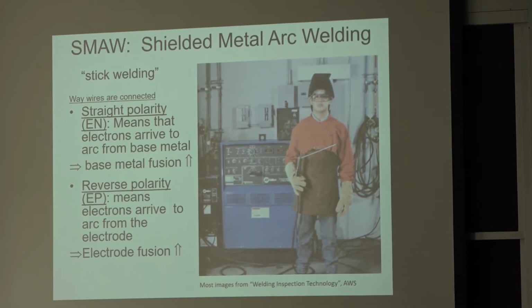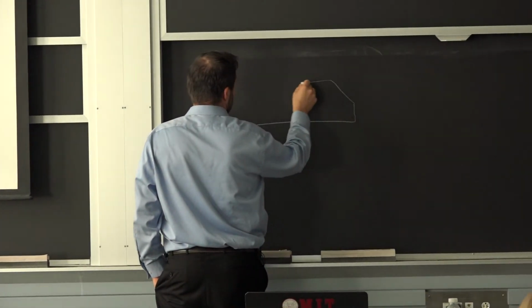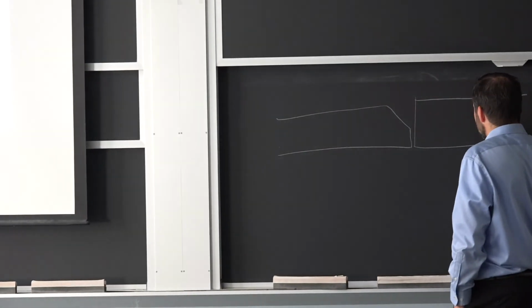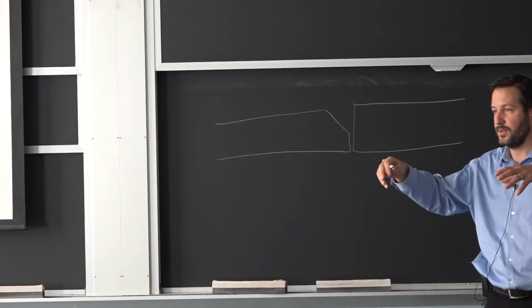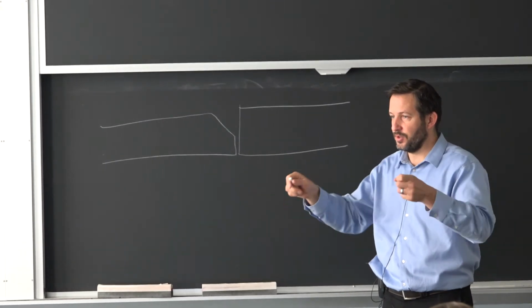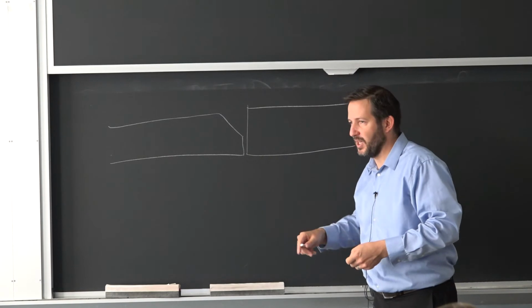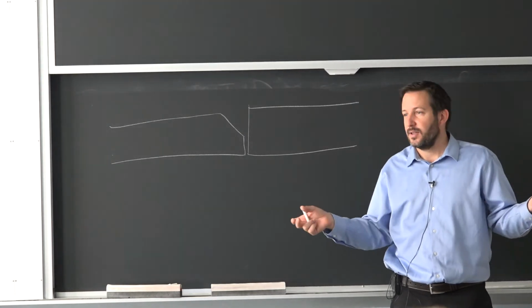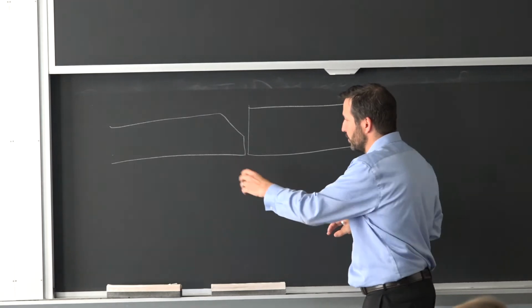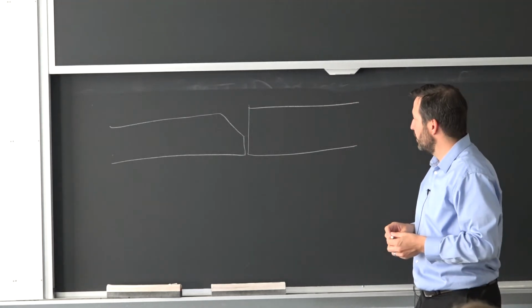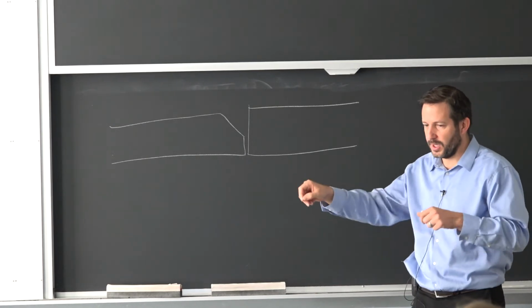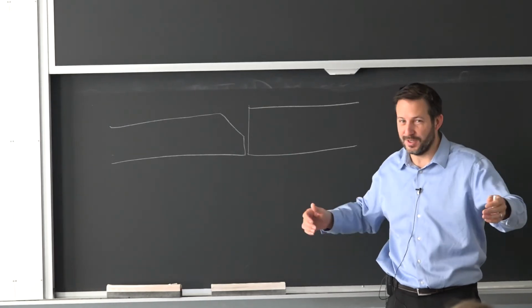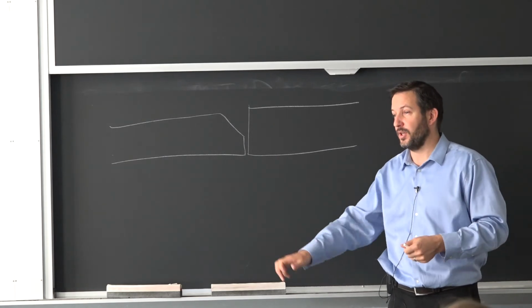So let's say it's on a thick plate. I come with one side, and let's say the other one. A lot of times when you're trying to weld assemblies, even in shops, you take all the pieces and put them together in a certain shape. Then you start welding and adjusting. You don't need these cuts to be absolutely precise. Actually, a lot of times you want a little gap between the pieces. You hold this here, you hold this there, and you start to tack weld, as we call it. You put a little weld here and there, and you can verify that overall your dimensions are correct. If not, you use a hammer and move things around, you use a press, and when you're happy with it, then you go in and complete the welding.